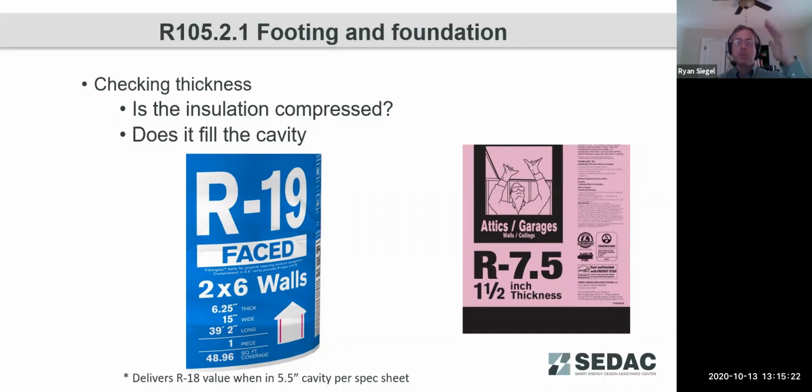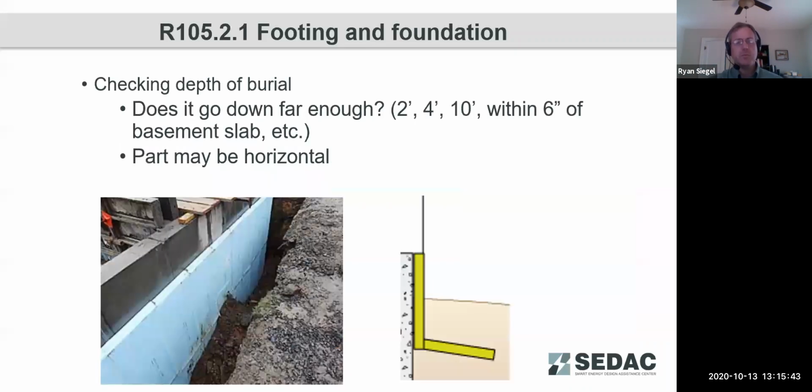So top, bottom, the 2 sides, and front and back. So we need to have it bounded. If we do not bound the insulation on all 6 sides, air currents can develop within this air permeable insulation, which will degrade its performance. So again, understanding what you're getting as you're doing it.